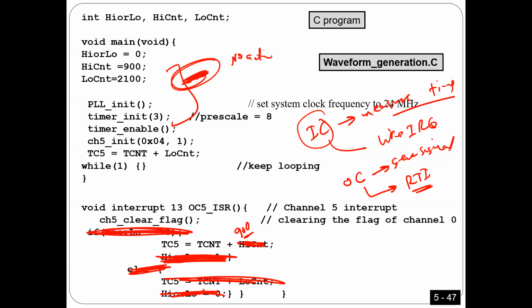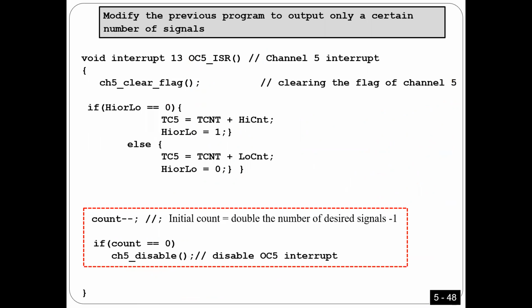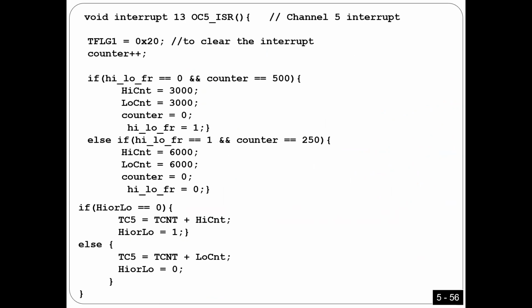Right now, if I make it 901, that means you are going to have an interrupt every 301 microseconds. Sorry, because every one you add is going to add 1/3 microsecond. So you can put whatever number you want here. Very easy, much easier than RTI. Is that okay, guys?